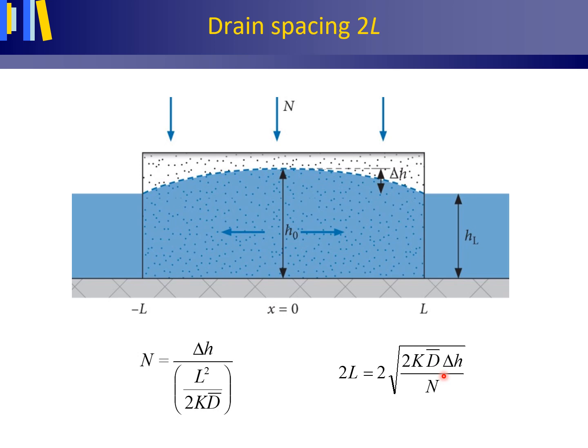As the land surface in polders should not be too wet in order to still allow for farming practices, this restricts the values for the convexity delta H. It is a very useful equation to determine the optimal distance between ditches that drain these polders. Typically, take the train from Utrecht to Amsterdam or for another part of the Western Netherlands, and you can see the meadows to be quite evenly partitioned by these ditches.